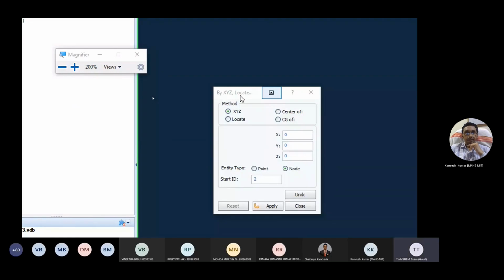Now let us get started with this. In the design document we referred to, it is mentioned that we have to elongate this antenna in the Z axis. So X and Y, I'm leaving as they are. I'm just changing my Z value. The Z value should be exactly half of the length specified in the design file. In the design file, it is mentioned as 337.8 mm, so you have to divide by exactly 2.